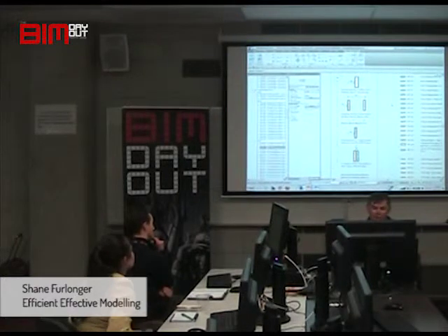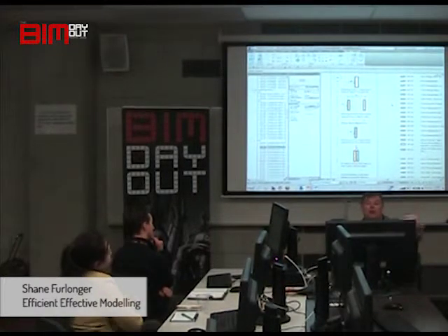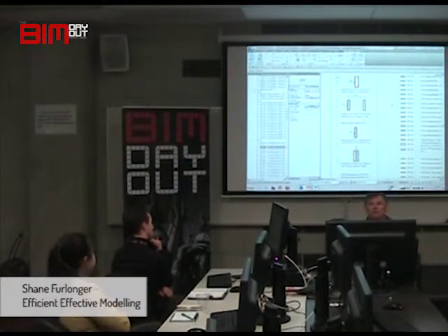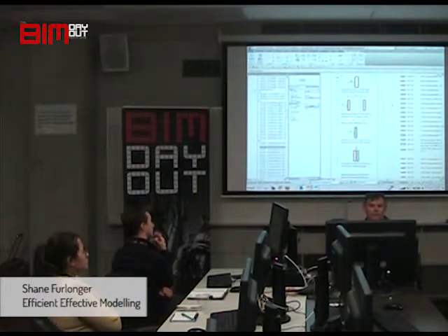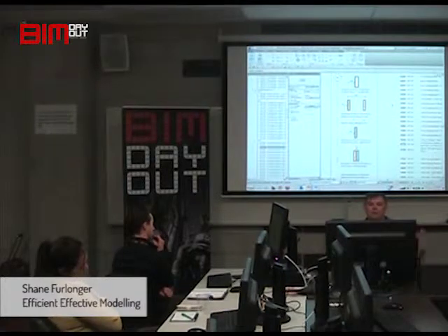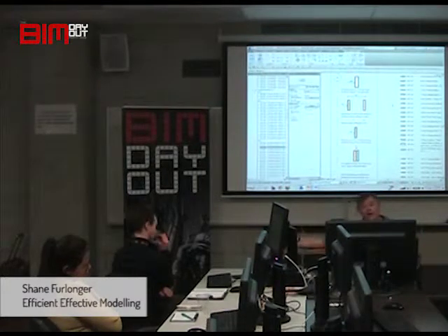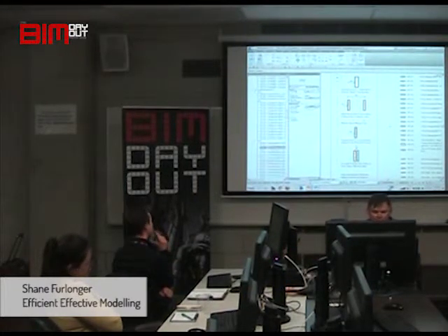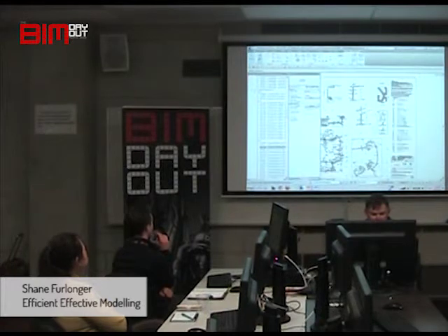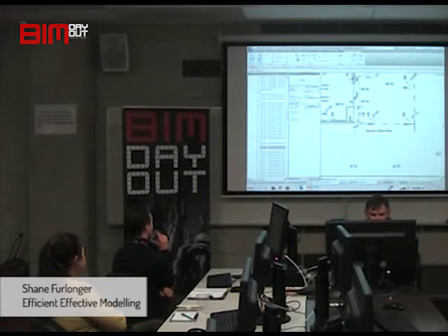So it was a lot of just keeping ahead of the builder as we were producing these drawings. So is that something you do in the future now, those dimensions? This is something I do because I know what the brickie wants. You know, any brickie is going to want those sorts of dimensions. He's going to want to know, like I said, where his openings are, how long his wall has to be, and a starting point. So his starting point's to the grid. And I make that quite clear with my set out points around the place, saying, here's a masonry set out point.